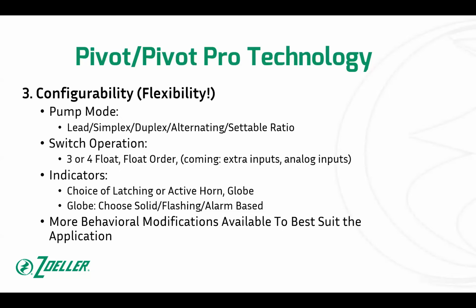So let's assume we've got a duplex panel here, and we look at the pump modes. I've got a bunch of different settings when I look at pump modes. I've got lead, simplex, duplex, alternating. Well, simplex, that's simple. I could put it into simplex just because I have a pump down, let's say. Actually, that you would do a different way. You'd do it right from the HOA.